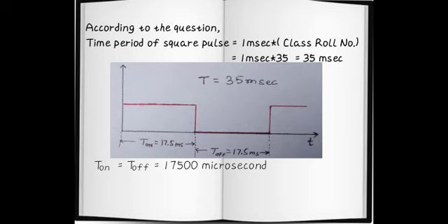So when registers TL0 and TH0 of timer 0 are set to a particular number and the timer is started, it counts up from the number set at TL0 and TH0 till the register overflows after FFFF, and the overflow flag TF0 is set and the count stops.